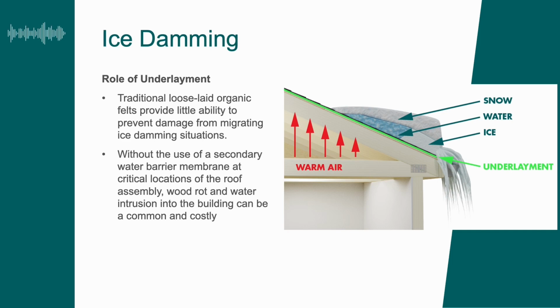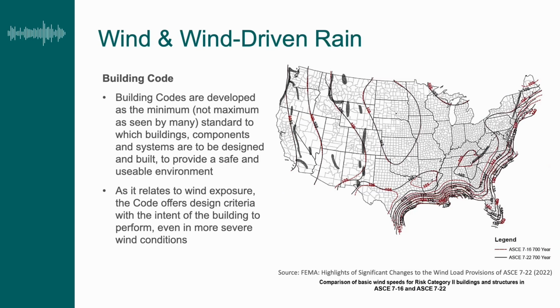self-adhesive underlayments, for example, or an ice barrier, say on your typical code, which is 24 inches inside the outside wall, that prevents that damage, because rarely are you going to see ice damming come more than 24 inches upslope on a roof. Typically, ice dam protection is required in areas where the average January mean temperature is 25 degrees or less.